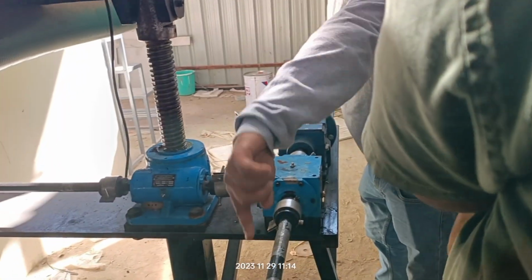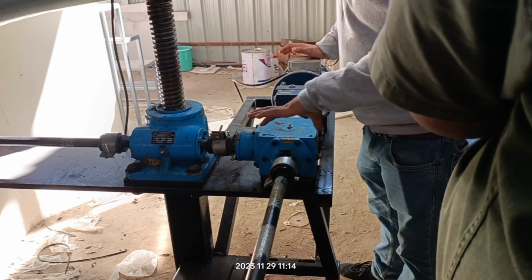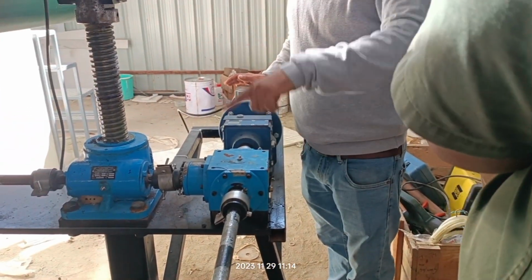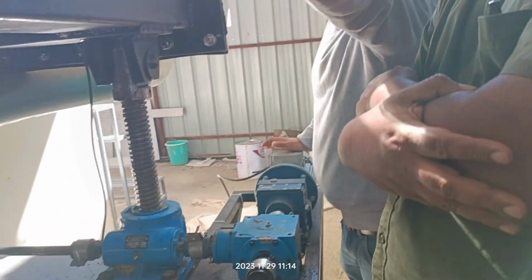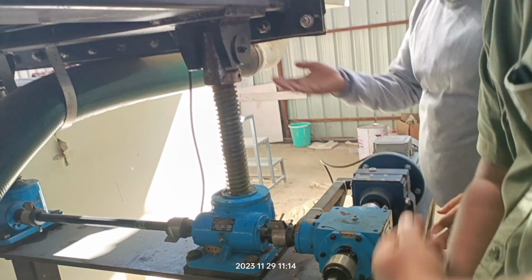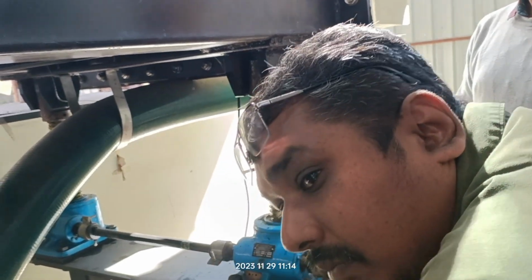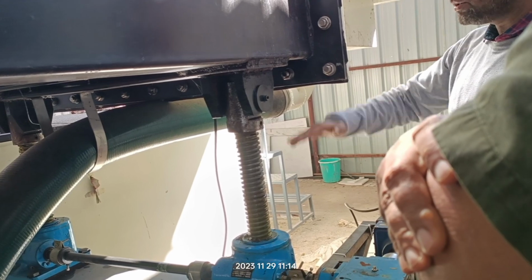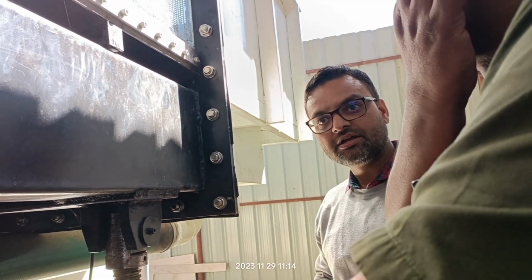These all are interconnected with the help of these gearboxes. And this gearbox has a ratio 1:1, then that has another ratio, that has a different ratio, that has a different ratio. So it is like that, if it lifts 300 mm, the last one will lift only 80 mm. So that's why we have created that tilting variance.